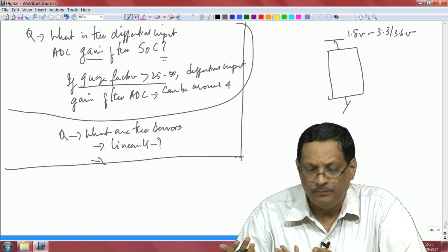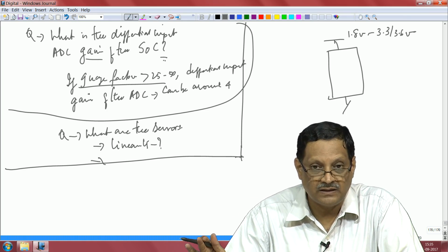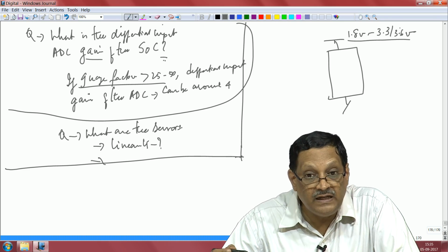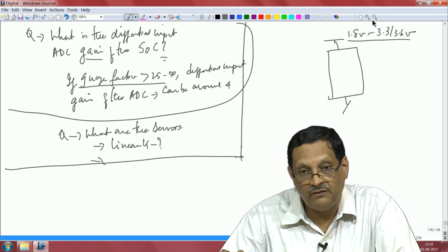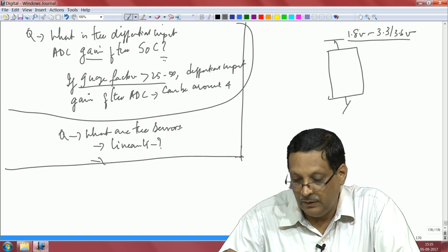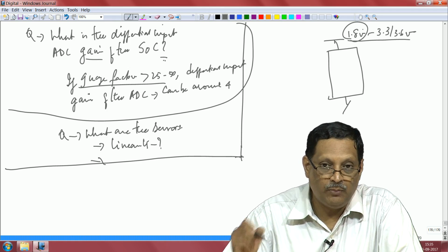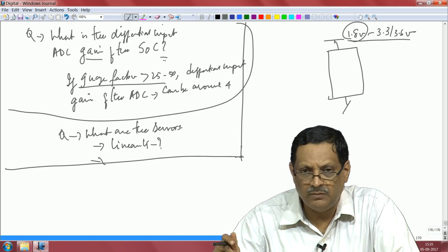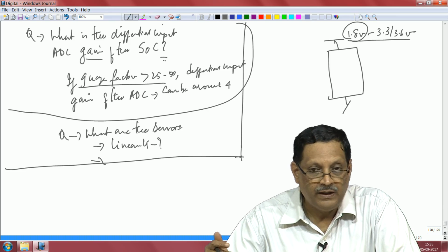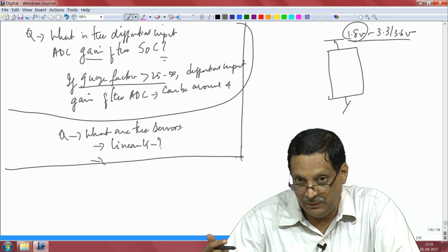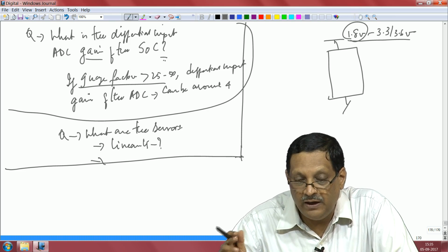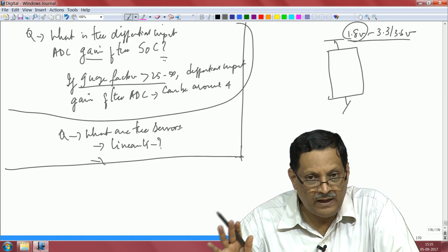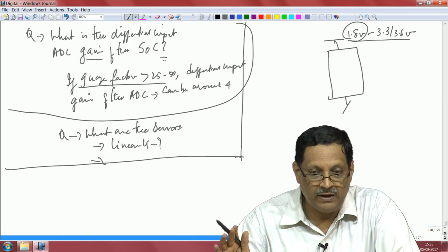So, you should find out whether this microcontroller can actually work successfully over a range of voltages. Obviously, certain functionality will be compromised if you are working at very low voltages. Okay, when I say very low, I mean in this order of 1.8, maybe certain blocks cannot work, but that still does not mean that you can't do, for example, some amount of compute may be still possible. So, again it will depend on what is your application, and really you have to focus a lot on the final application of interest before you actually choose the microcontroller.